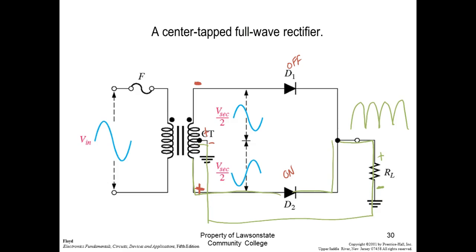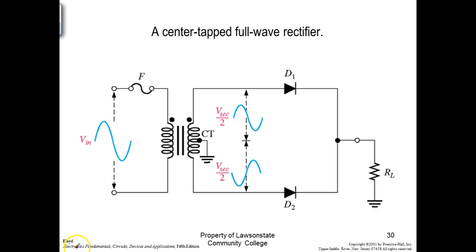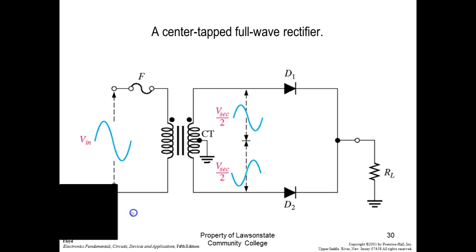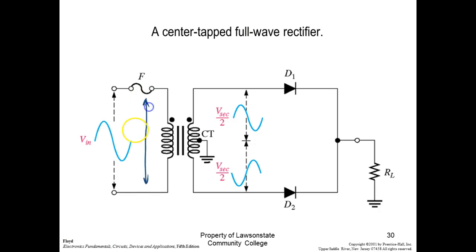So now we're dealing with what we call a full wave center tap transformer. Okay, guys, so let's figure out what the DC voltage will be, and then we'll take a break. So what are we putting on the input? The transformer is rated at 110 volts. It's a 12.6 volt center tap transformer. That's 110 volts, 1 amp.